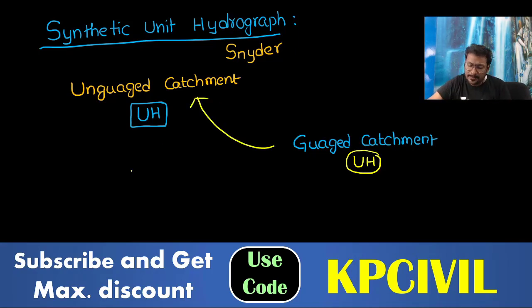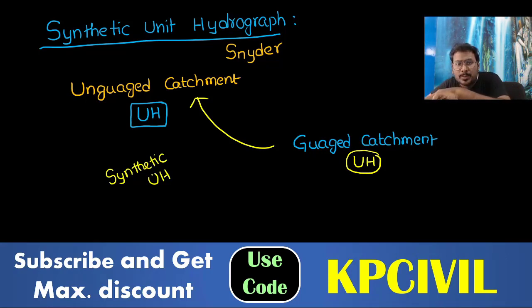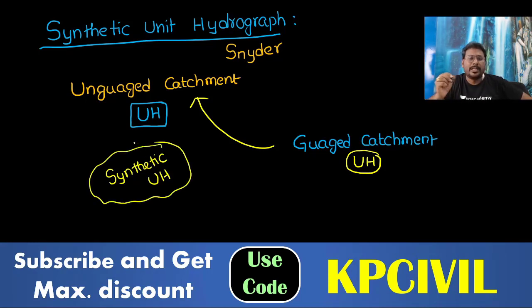That method is called the synthetic unit hydrograph, artificially made. You do not have any natural values; you get the values by comparing with an already available gauged catchment. So the unit hydrograph of a catchment without rain gauges, obtained using the unit hydrograph of a catchment with rain gauge, is called the synthetic unit hydrograph.